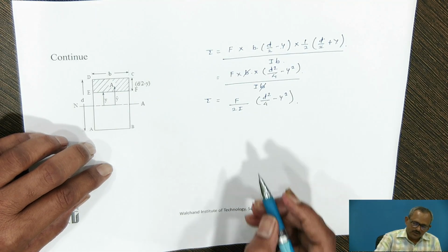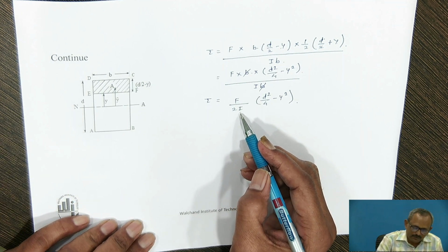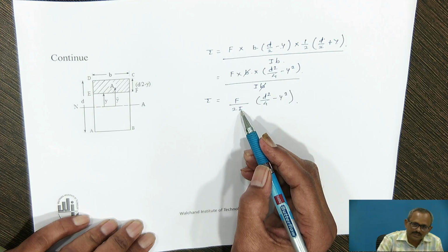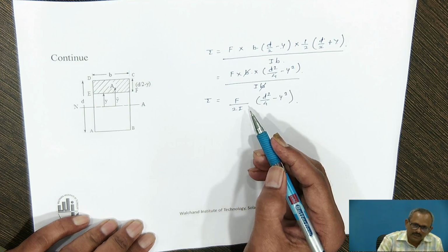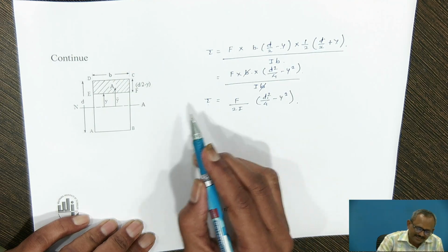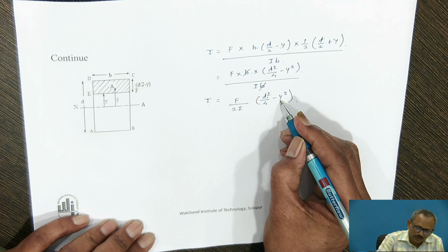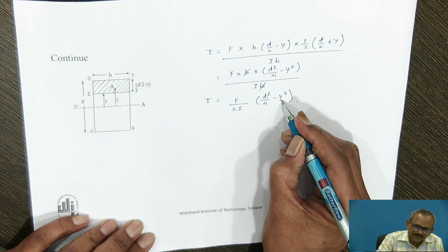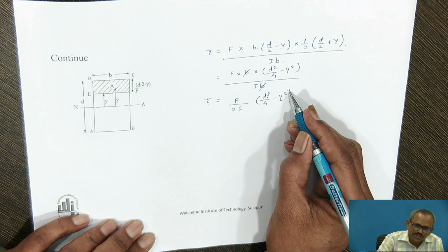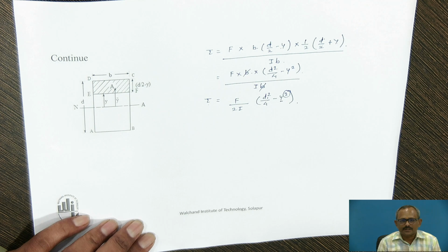Okay. So for the given section, the shear force is constant. For the given dimensions of the beam, the moment of inertia about the neutral axis is also constant. The depth of the section is also constant. So shear stress at any level varies according to the distance of that layer from the neutral axis, and the variation in the shear stress takes place according to a parabolic curve.